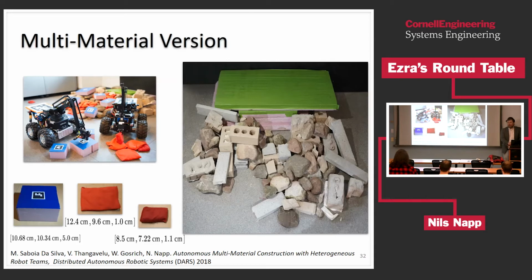Great question. So the question is, our 3D sensors are necessarily going to be discretized at some point, and our planning is this continuous formulation. So we do have to think about how to discretize, right? For example, if I have some sensing error epsilon, that plays into what the delta is for the individual discretization cells, and it's something that we have to hand tune at this point. So we want to formulate everything in a continuous space, and then when we implement it, we figure out the implications of specific discretizations.